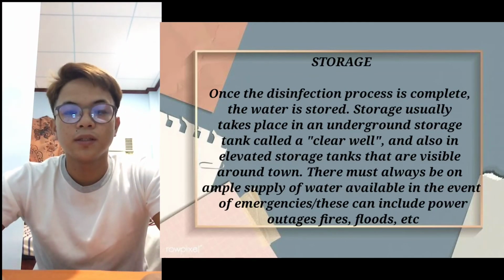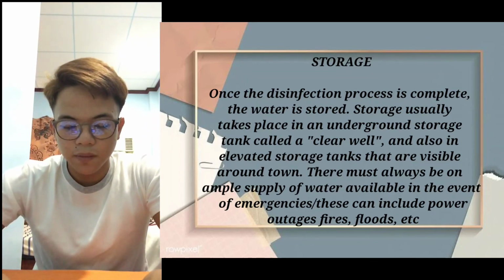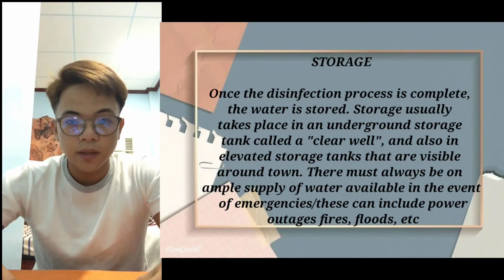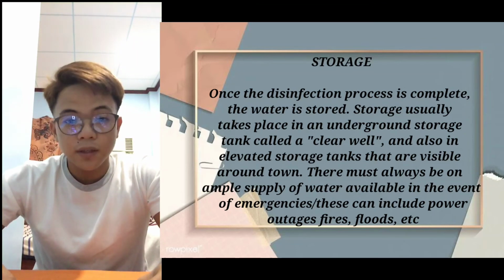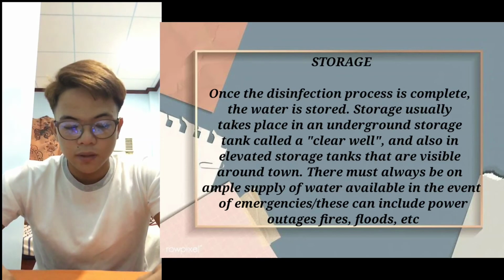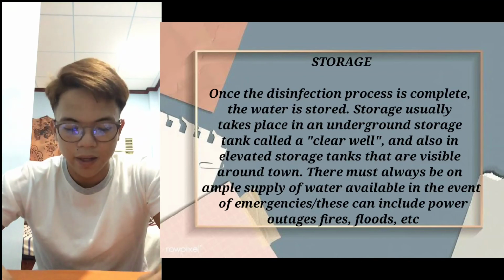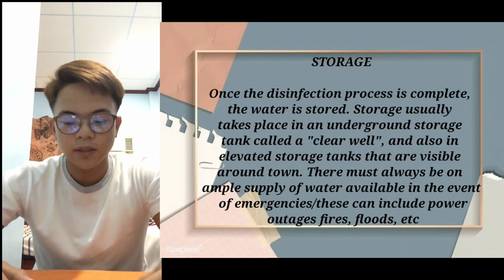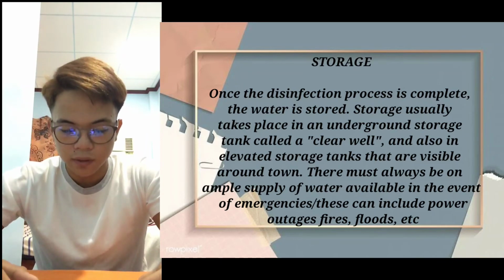Second one is storage. Once the disinfection process is complete, the water is stored. Storage usually takes place in an underground storage tank called a clear well, and also in elevated storage tanks that are visible around town.